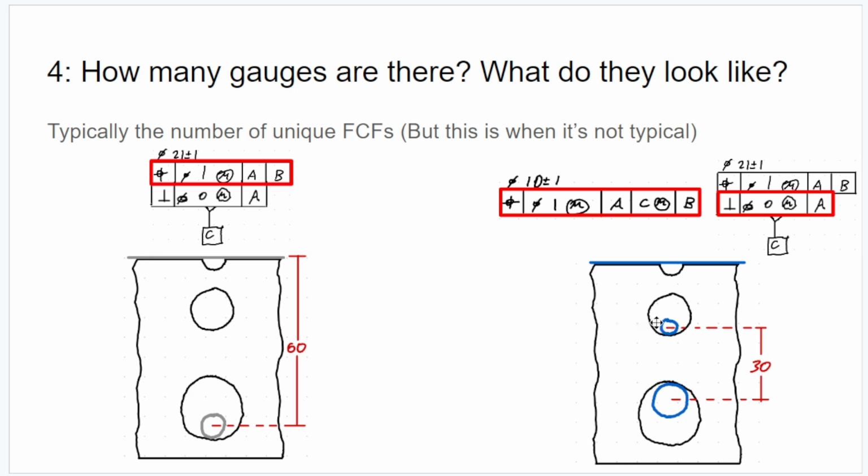This virtual condition pin is, of course, with respect to the true position, but this virtual condition pin is with respect to the perpendicularity. And this is why in the previous video I said that you can't just blindly assume that the virtual condition pins between 2 gauges are going to be the same, for cases like this where you have some sort of refinement.